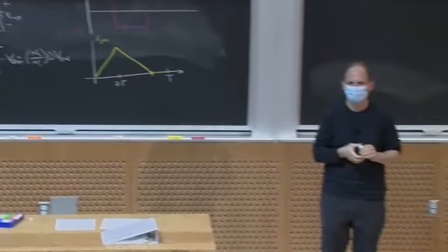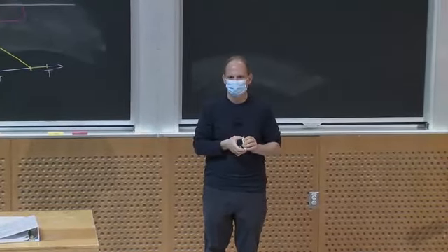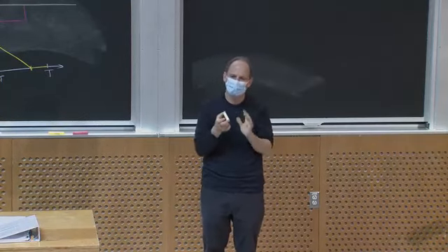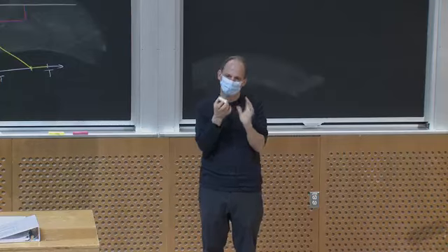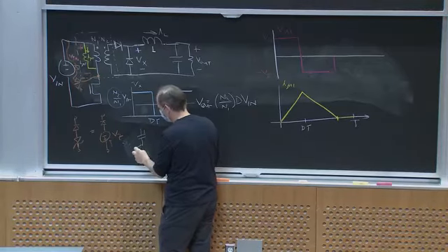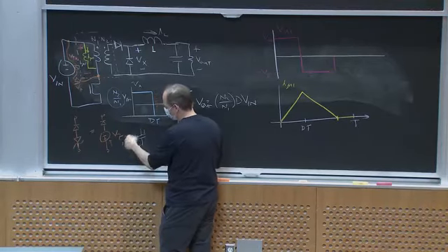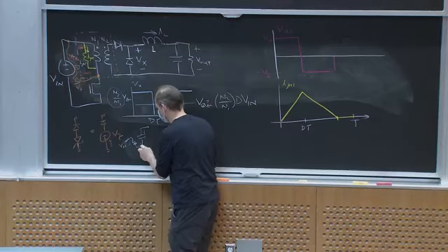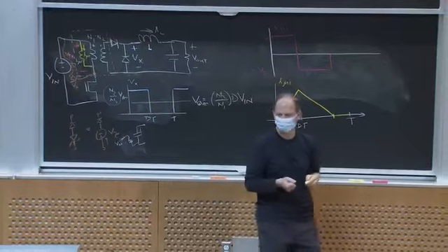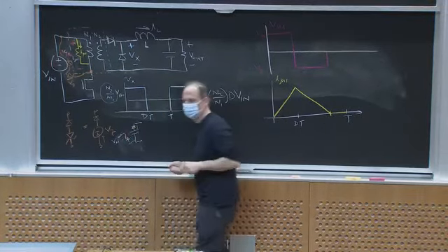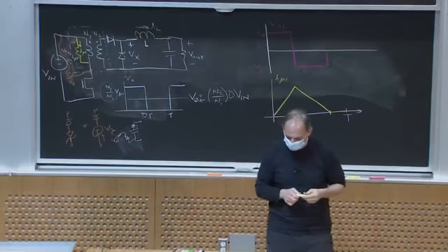So in this case, is the Zener diode just acting like a sink, like a resistor? It's just acting like a resistor, except that it's a fixed voltage. It clamps it. And you could replace that with a capacitor and then bleed that capacitor back down to some average value like Vn. Right? So you could have connected it like this too. Okay? You would have still needed a diode there.